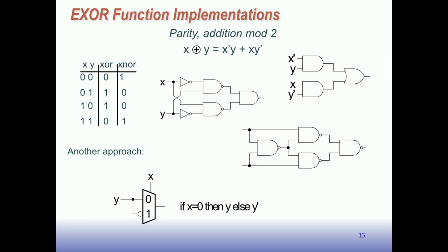It looks like this function back here, but then it has this extra NAND gate here, which serves the purpose of those 2 inverters. It's not actually fewer transistors than this. It's the same number of transistors, but I think it looks cool. It has a nice symmetry to it.